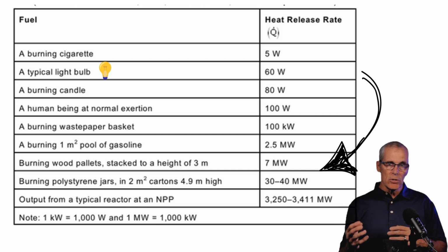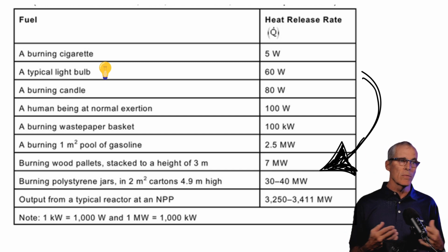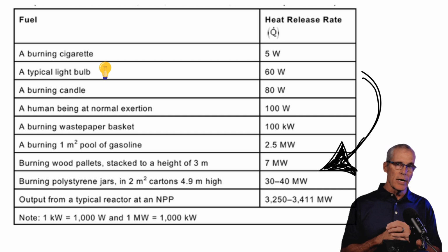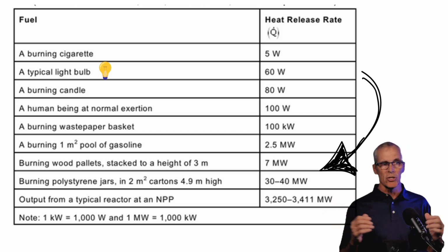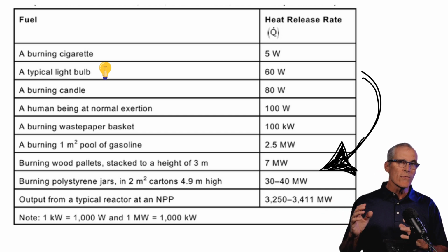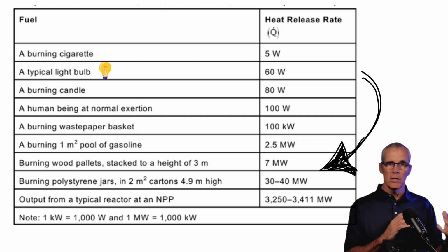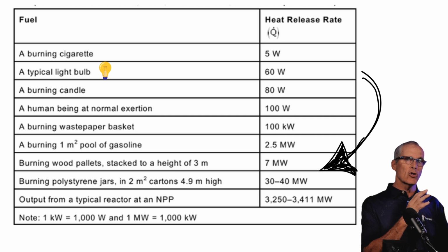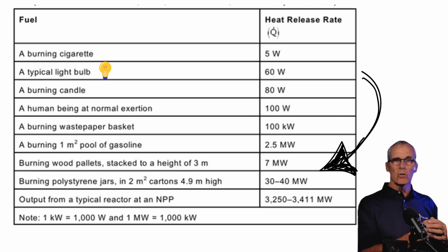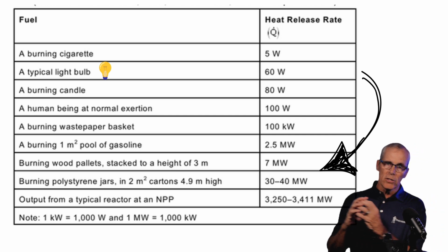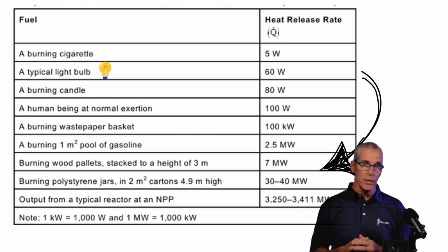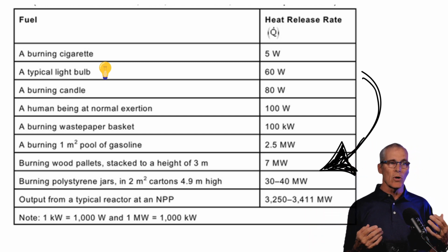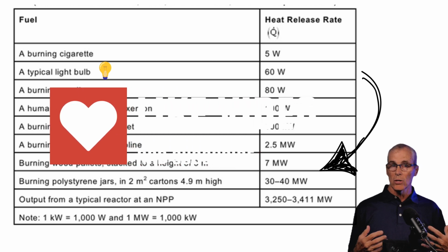So this kind of puts it into human terms, these are heat release rates, and it gives you an idea of how fast heat comes from an object. There's another factor that plays into this analysis. We're trying to get an idea of how big of a fire a transformer fire can be so that we have a handle on what it's going to do to our target, the control building. And this is just how we describe how big that fire is. We talk about it in terms of watts or megawatts or kilowatts.